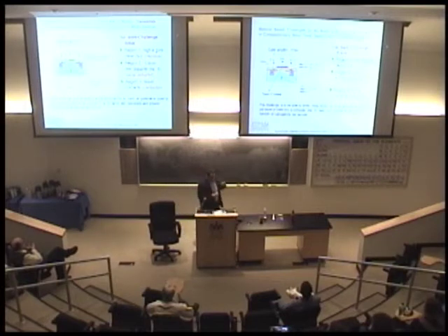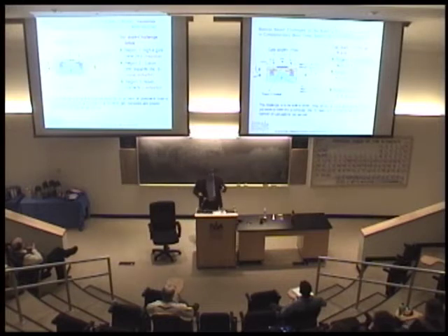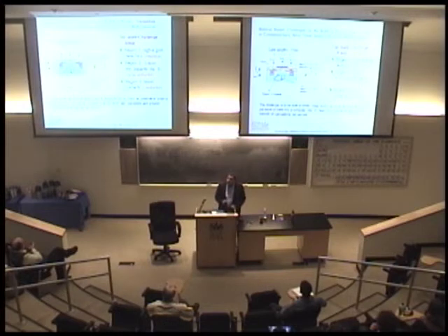And that's coming with the transistor, okay? This device is called the CMOS device, complementary metal oxide semiconductor, MOSFET, is doing that. You have an input, let's say 1 or 0, you get a 1 or 0 output. It's going to be either on state or off state, okay? How? This is just a semiconductor material. You have some open areas and then P-type silicon or germanium. And you have some metal, the blue regions, typical contacts. You have some oxides, the yellow regions, insulators.